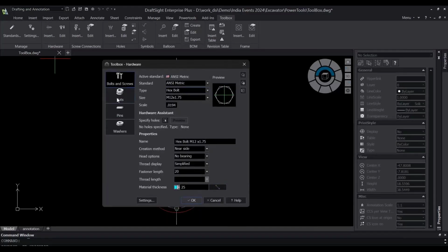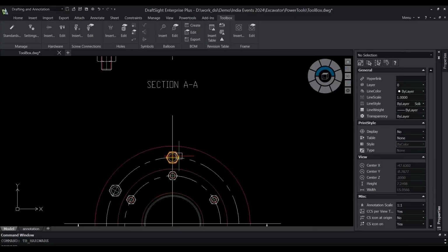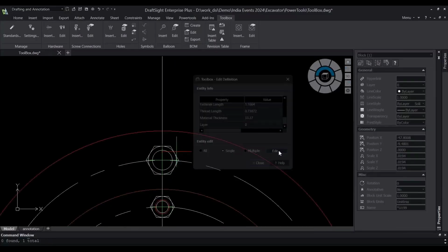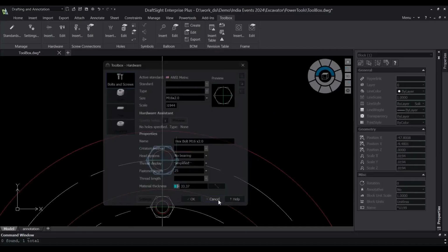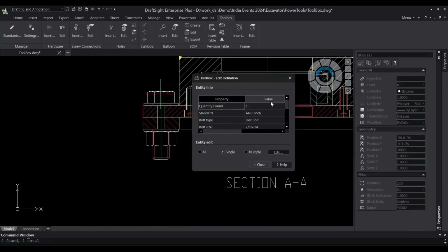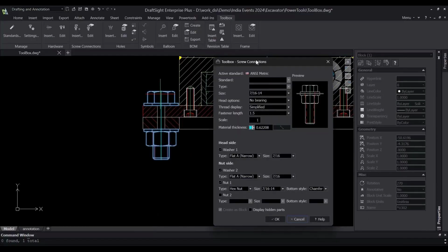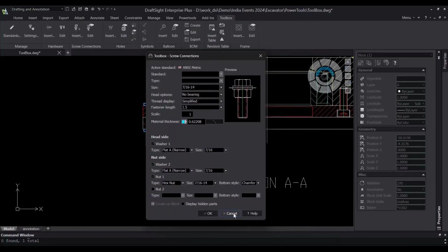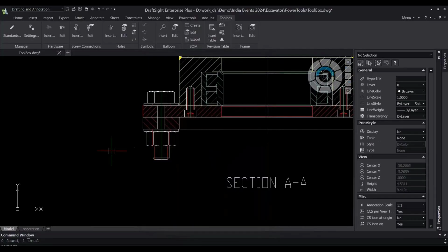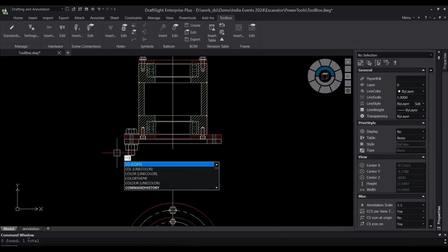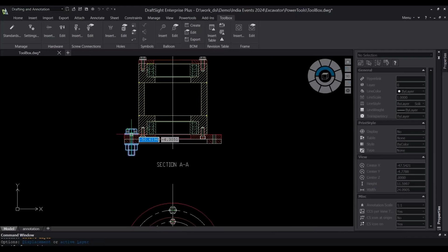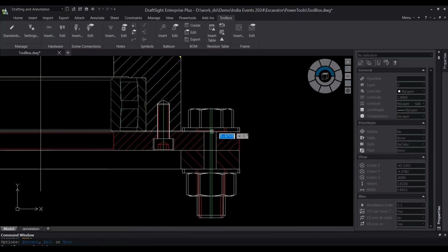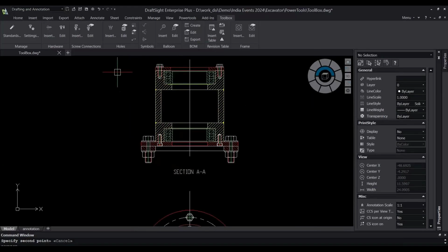And you can see over here, a complete library of toolbox is available, wherein different kinds of screws and nuts and all that stuff are available. You just have to select the block, and your complete block directly gets placed in your drawing. So you don't have to worry about creating those or creating a library for this. Not only just a simple toolbox, a toolbox with your screws and different kinds of nuts, fasteners attached to it could also be created. So once I've created it, I can make multiple copies out of it.